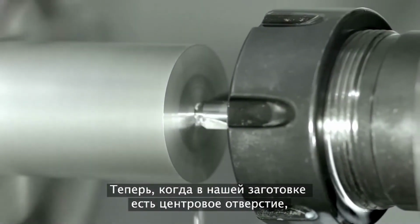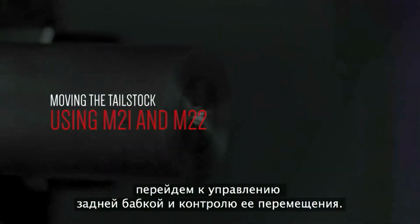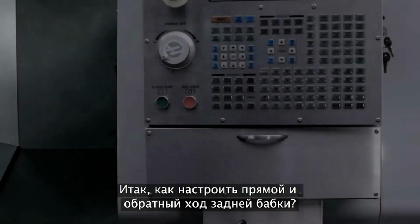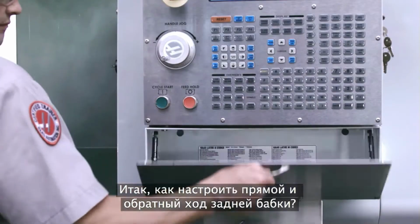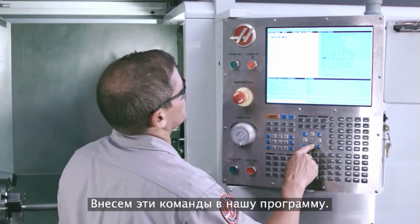Always use a 60-degree center drill, so the angle of the drilled hole will perfectly match the angle of the live center. Now that our part has a center hole, let's move on to how we command our tailstock and control where it moves. So how would you tell the tailstock to move forward and retract? M21 is the tailstock advance command, and M22 is the tailstock retract command. Let's add these commands to our program.